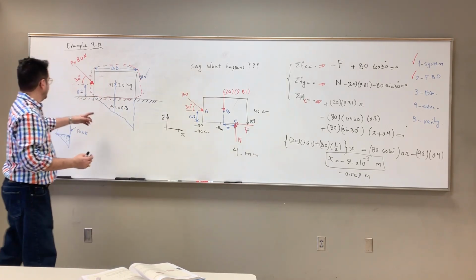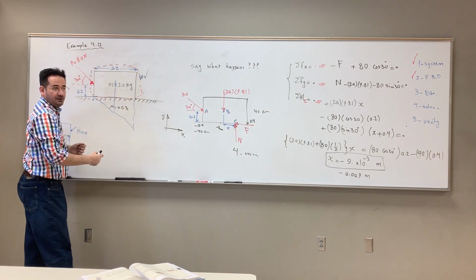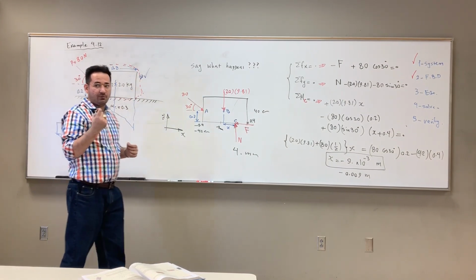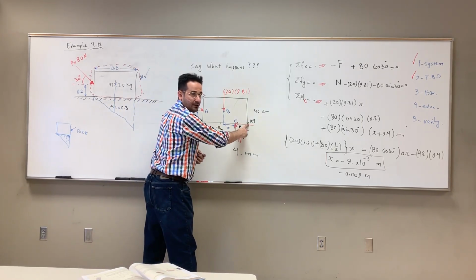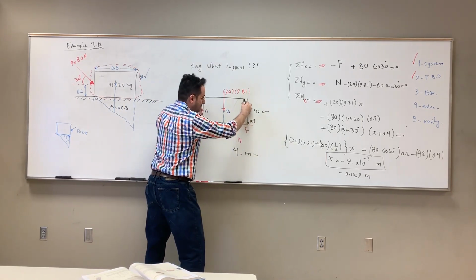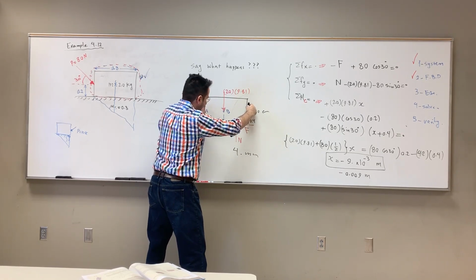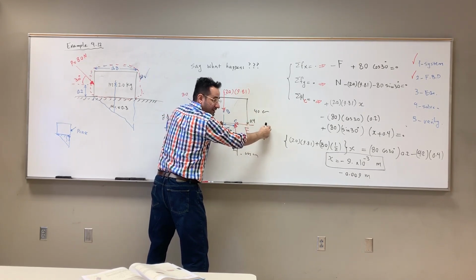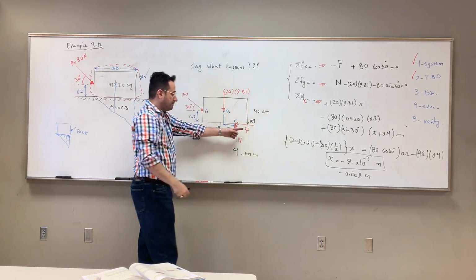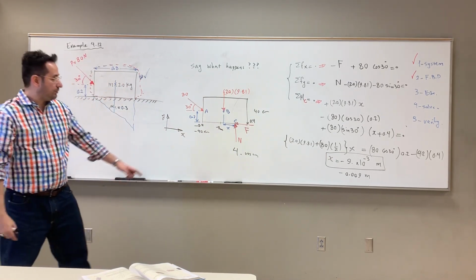Which means that this thing is going to roll. Because the maximum possible that x can have is 0.4. And if it's greater than that, this thing will start to tip over, right? One side goes up. This thing will start to tip over if x is greater than that. So x must be within the range. The maximum x is 0.4.